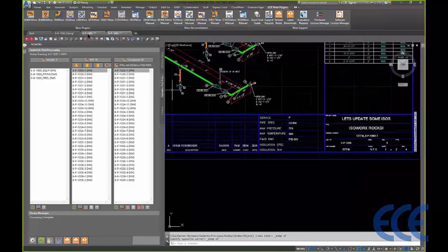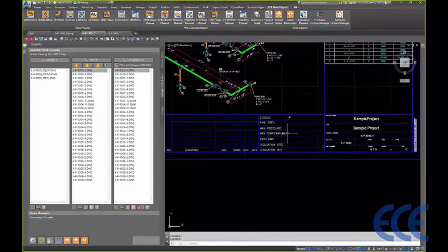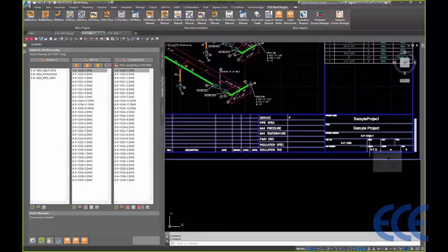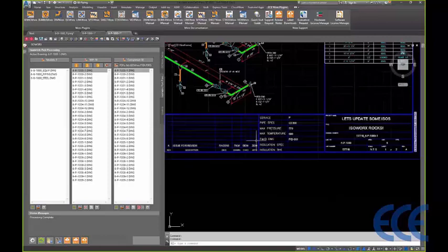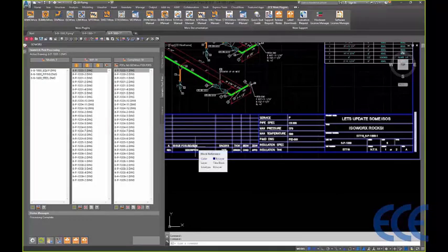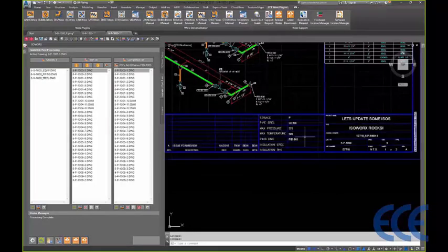So at this point, you can see we've been able to take a standard title block with whatever comes with it. You can fill out some of the information if it's consistent across the board, and then update it with new information all the way through. So a lot of this is going to stay static once you've ran it 1 or 2 times, but you are going to be updating your revisions quite frequently. But it's nice to be able to manipulate all of this data just from an Excel spreadsheet.